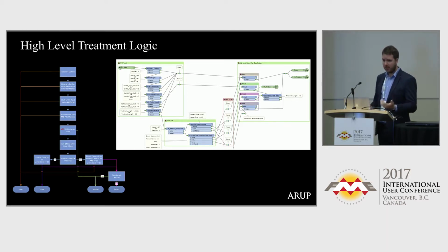But that would also take into account things like how it interacted with the alignment. And then we also took into account things like cover as well. So it might be acceptable, might be underneath the design enough, or the track slab enough, but the actual cover between the two, we couldn't fit in a protection slab or anything like that, so it would actually be a divert from there. Other cool things on that as well was if the protection length was over 20 metres, we would actually revert that back to being a manual, because protection slabs over 20 metres get pretty costly as well.